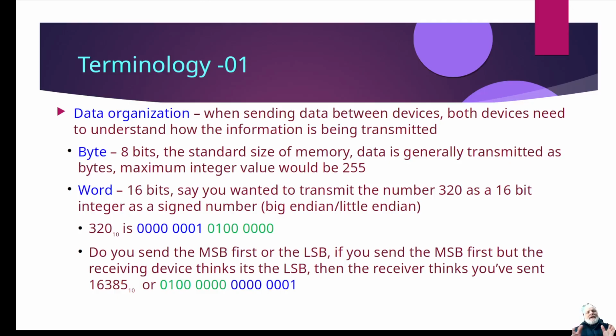But our PLCs are only 32 bits, so when you're working between 64-bit machines and 32-bit machines, or even microcontrollers that might only be 16-bit, there's a bit of a distinction there between a 16-bit word and a quad word, which is 64 bits.